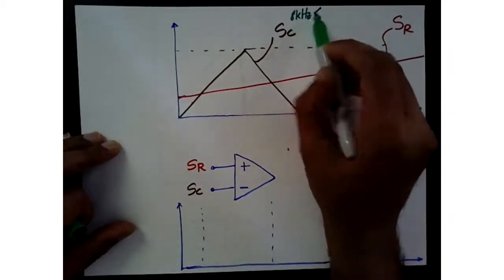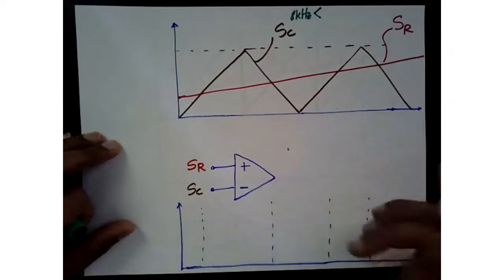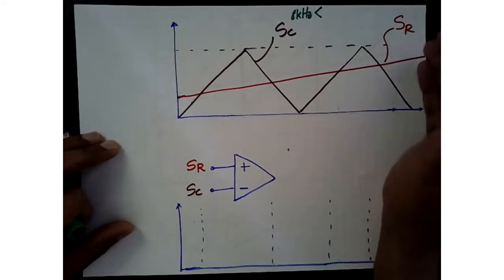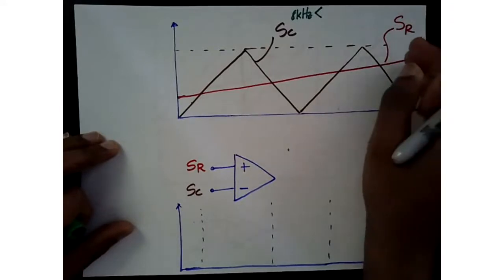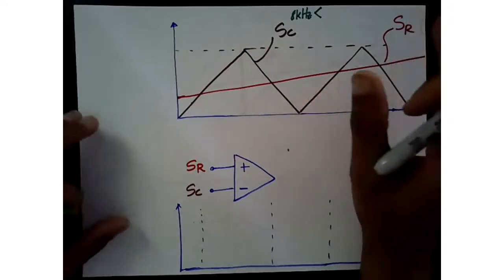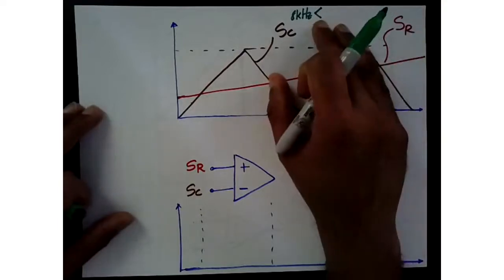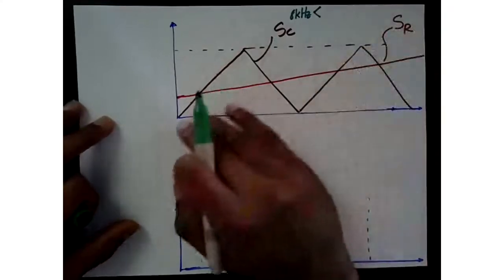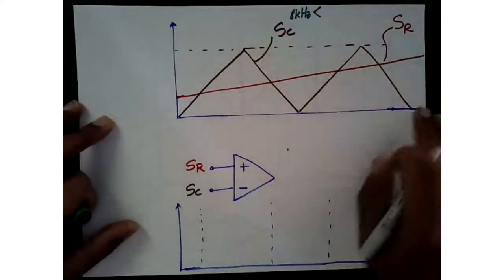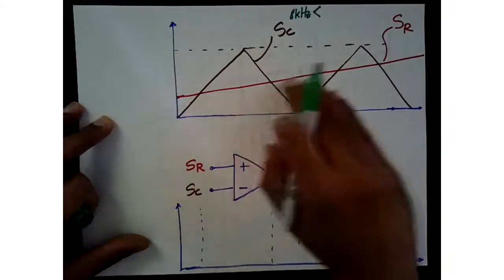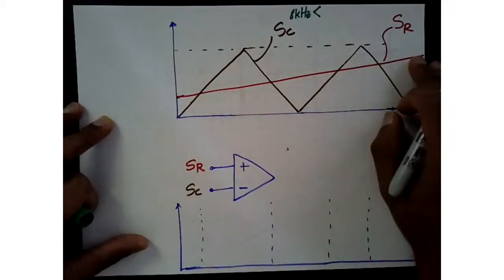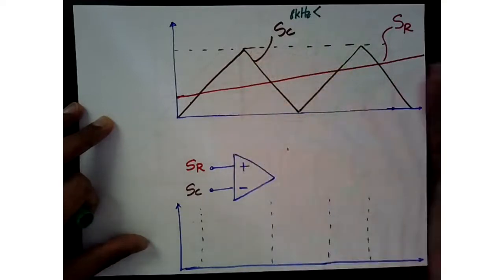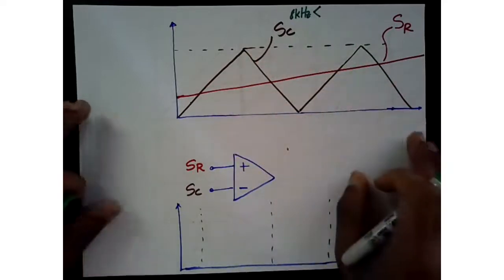The reason behind that is you don't want to have an audible signal. That's one reason. And then as you increase your frequency, we know that our switching losses increase. So we have to manage the switching losses as well as the audible noise when it comes to certain applications. Keep that in mind. First of all, we look at this triangular waveform, and we need to apply a reference signal which gets compared to the triangular waveform so that it gets converted to PWM.